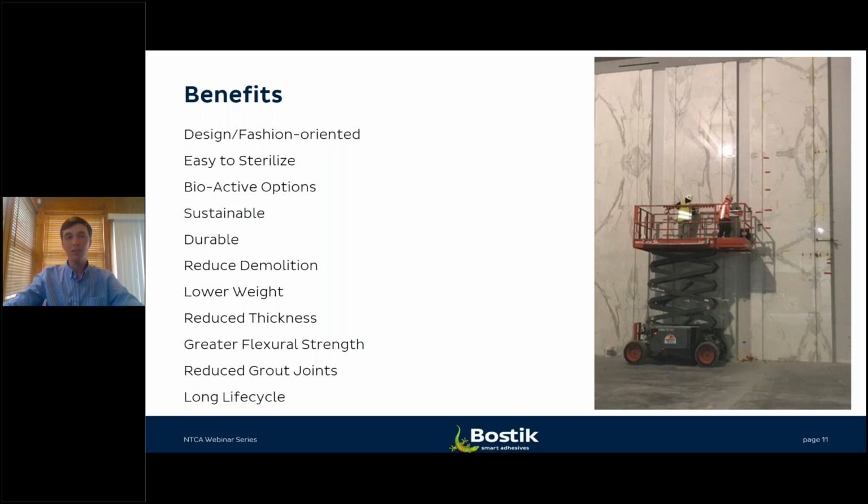There's sustainability aspects to gauge porcelain tile, quite a few of them as well. I mean, they contribute towards indoor air quality by not harboring dust. Anything that gets onto a tile sits at the surface. They're known as hypoallergenic, low VOC, and they have a relatively low life cycle cost as well. So they have a long life cycle and a relatively low cost for the overall installation as well.